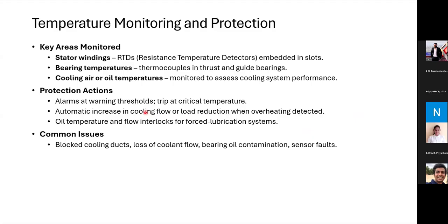Temperature monitoring and protection: the key areas that are being monitored are the stator windings. We have resistance temperature detectors embedded in the slots to look at the stator winding temperature. Bearing temperatures, as explained, are measured with thermocouples, and cooling air or oil temperatures are monitored to assess the cooling system